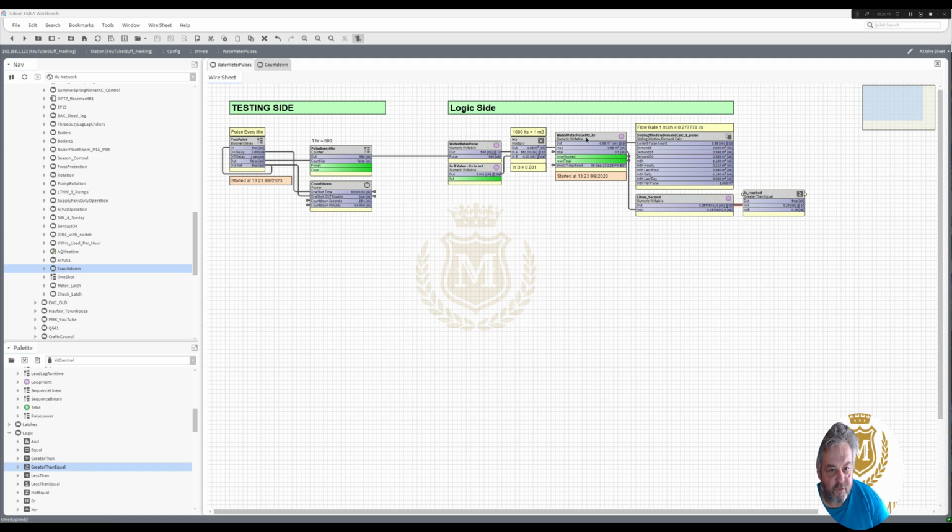I would use this block here, and I would add to it the numeric totalizer, because it's near enough there on the litres per second for an hour, meters cubed an hour. But yes, we've gone above it. It's 2927, and we've still got 1 more pulse to go in another 55 seconds to reach the 600.